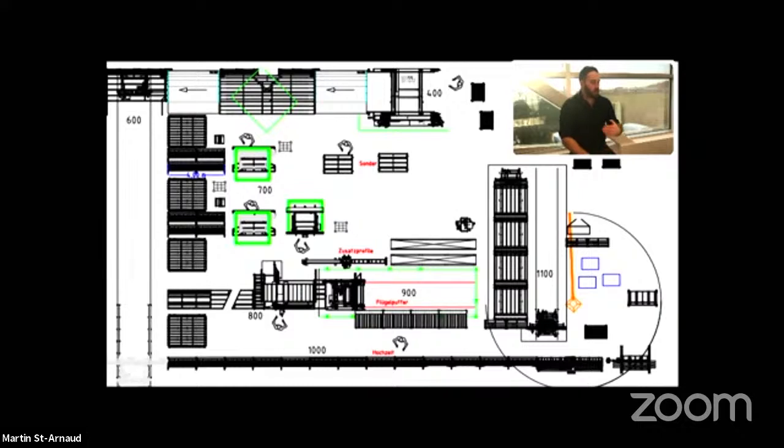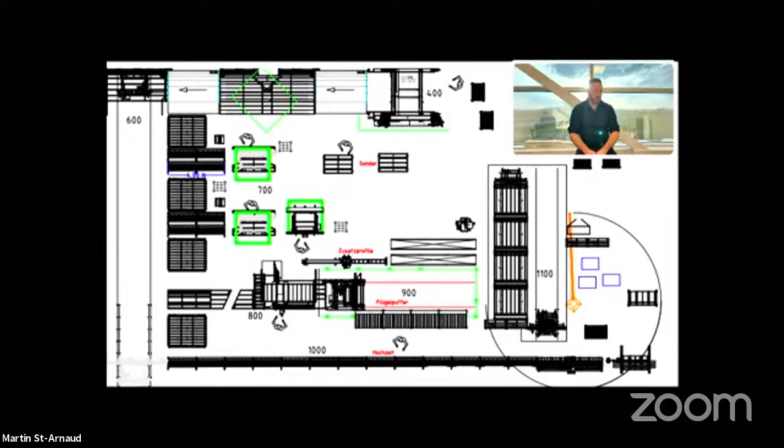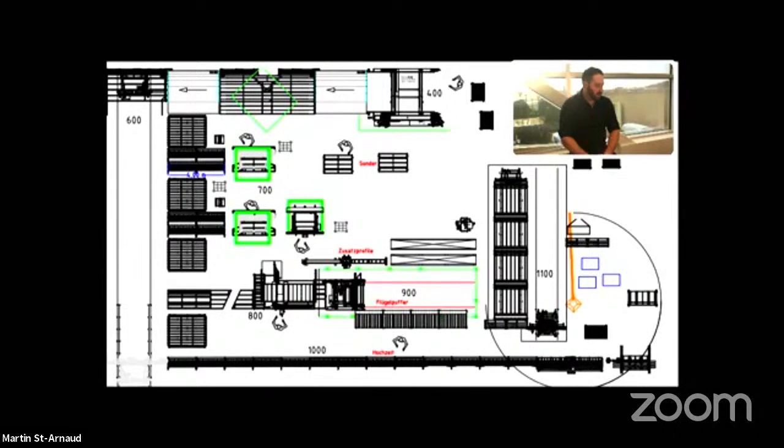If you're looking at the top of the screen, you're going to have one employee loading the welder, unloading to a single head corner cleaner with turning station. And if you're thinking that a frame is on it at this point, what the frame is going to do is it's going to be automatically unloaded by the buffer that's on the left of the screen. Then it's going to make its way to the tables that are in the middle of the screen. Employees are going to be assembling the frame, putting it back to the buffer. Buffer is going to bring the frame all the way down on the screen to the vertical table there.